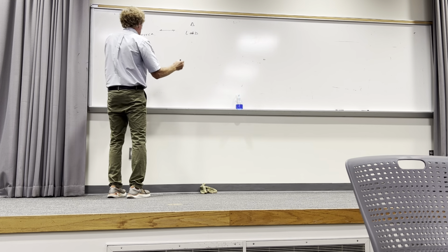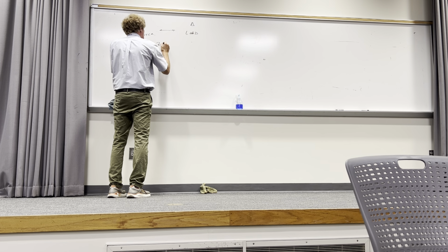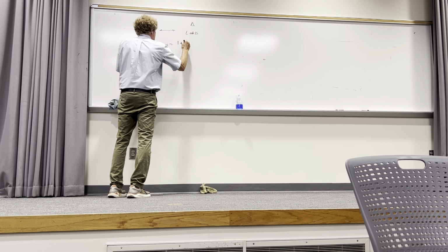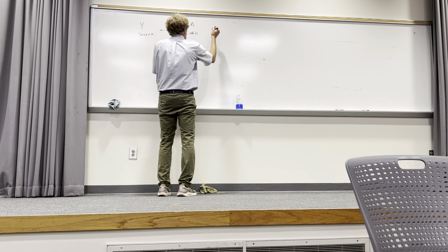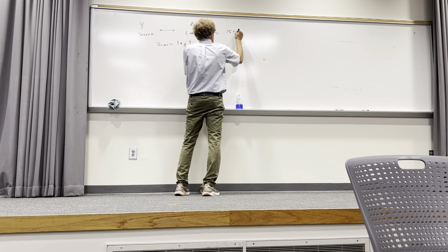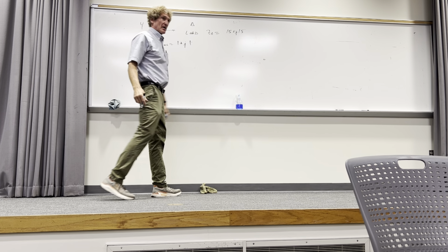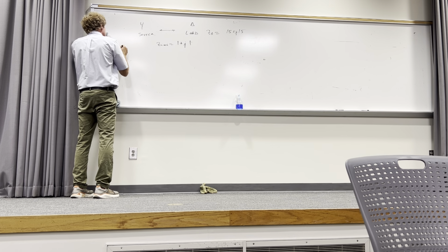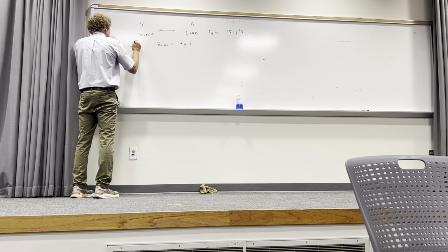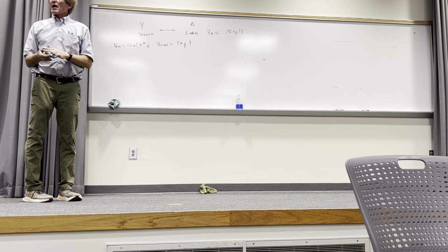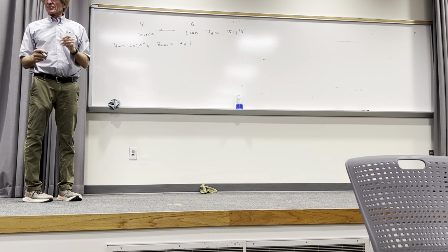And I'm going to say the line impedance is just, I'll call it 1 plus J1. And say the delta load, Z delta, is equal to 15 plus J15 ohms. You know why I've chosen that already. And I'm going to say the Y source voltage, VAN, is 120 at an angle of 0 degrees, volts RMS. Y'all with me? So now we're going to draw the equivalent YY first. Y'all follow me on this.